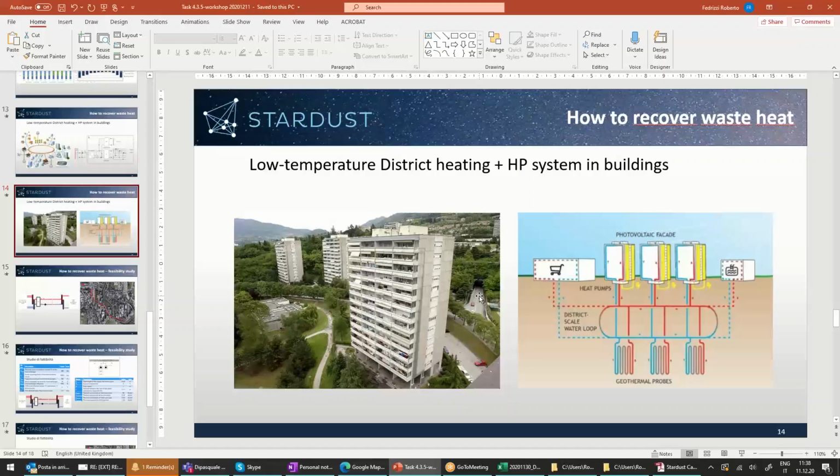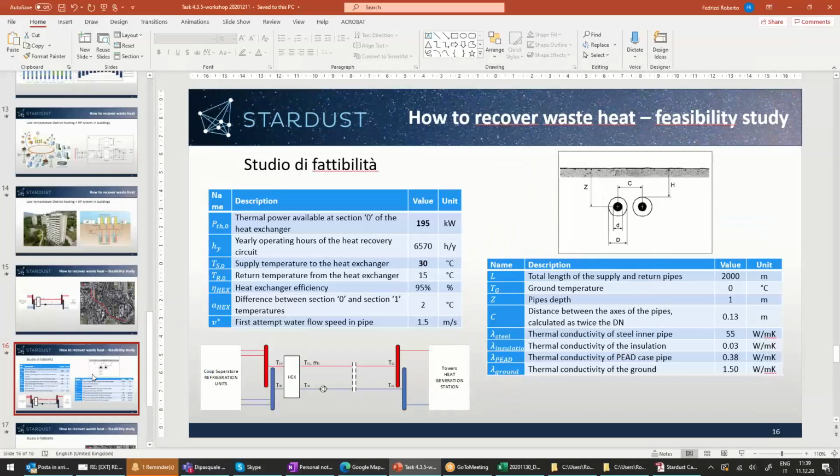And that is very effective because, again, you can drive this low temperature network with the high temperature network also during summertime. And again, you can use this technique to extend the high temperature network where this would not be viable from the economic perspective. So it is not said that the entire network needs to be high temperature. And this, I think, replies to the first question.